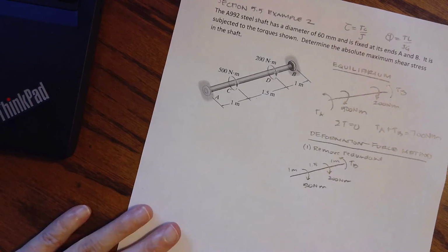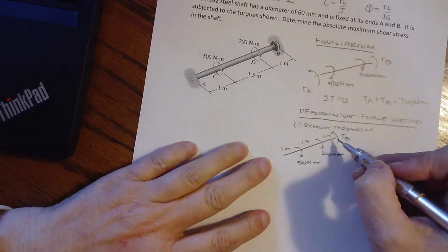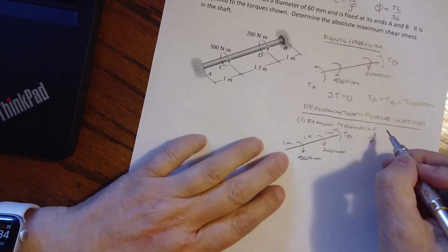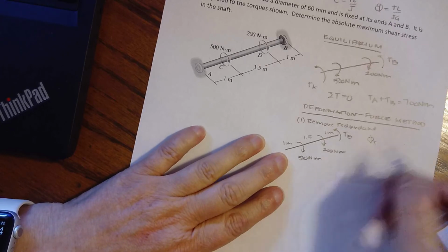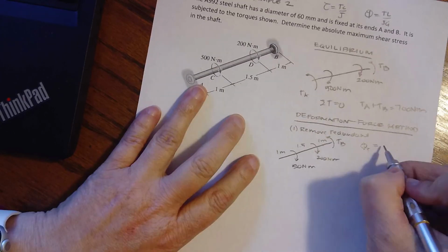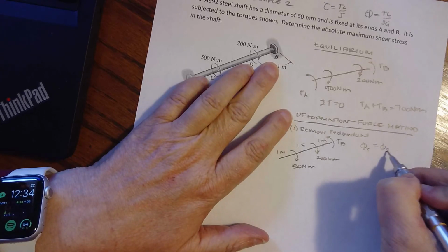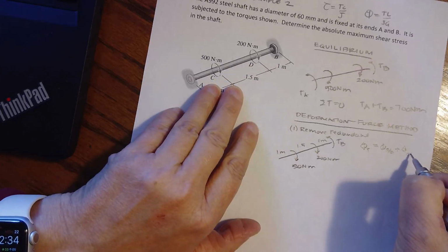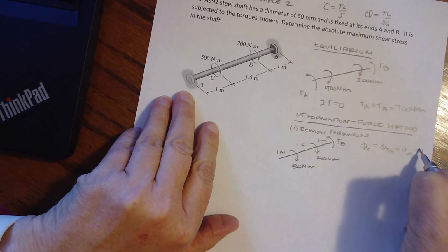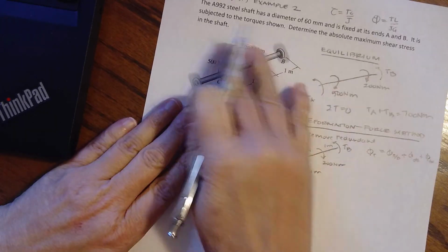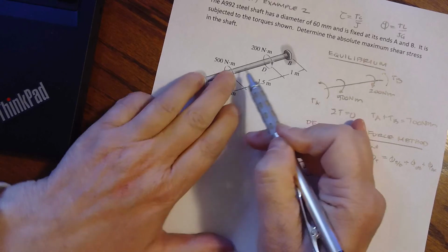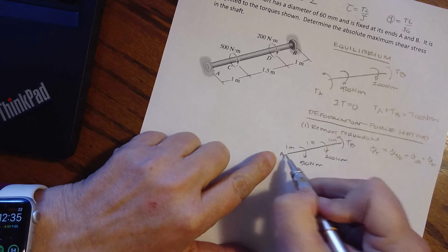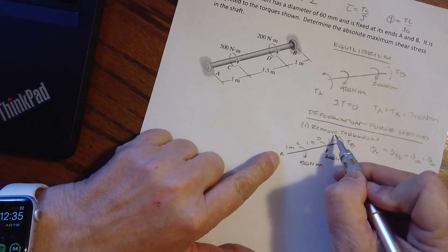So now I have to figure out, well, what kind of twist are we having? If this is free to rotate now, I can see that I'm going to get a phi that comes from the torques that are applied. We're going to have to sum up the phi from B to D plus phi from C to D, plus phi from A to C. As we're twisting this, it's because we're applying these torques here, and it's going to change the amount of torque we have in each segment. So let's start here at A. So we have A, C, D, and B.